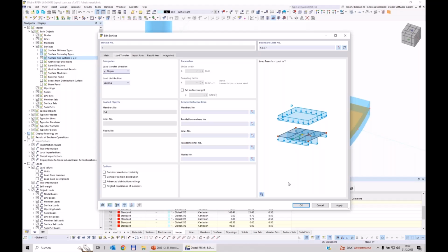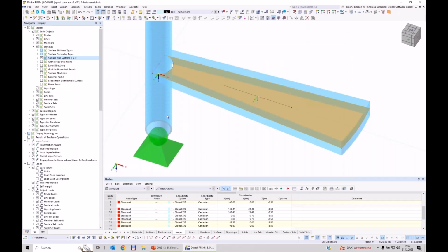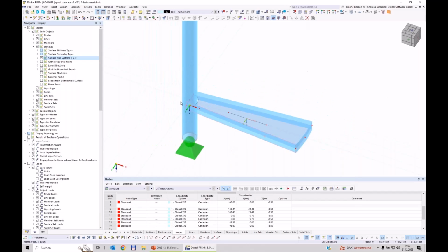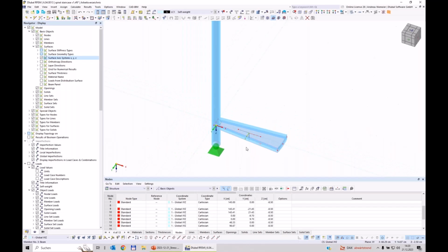let's say, supporting elements. And further, I specify this surface have a weight for the self-weight load case. So let's say 0.2, 20 kilos I apply. Now, so far, so good. We have now modeled a stair step, like a cake segment, what we can now in the next step copy and rotate around the pole.